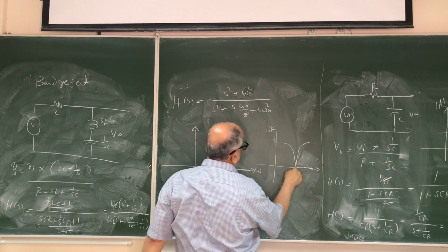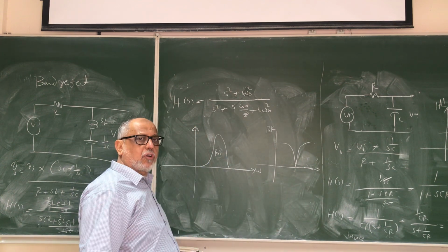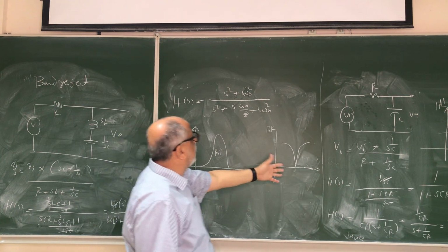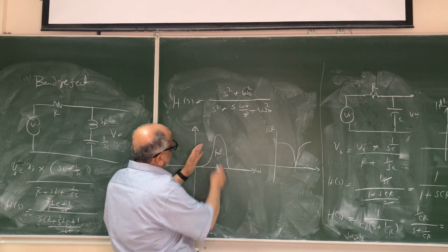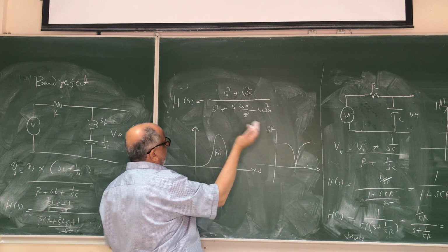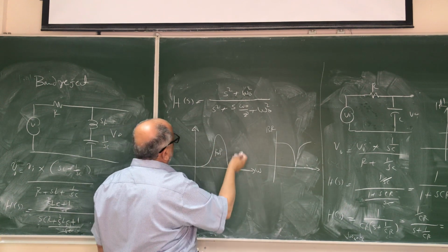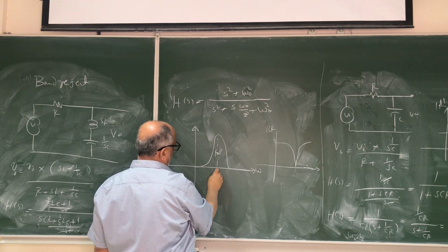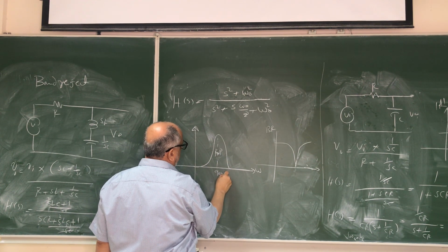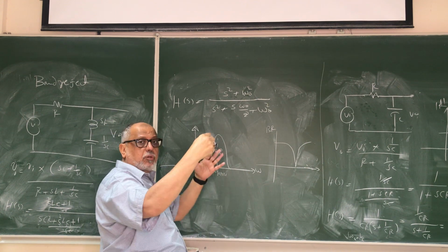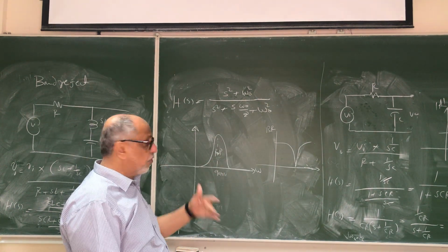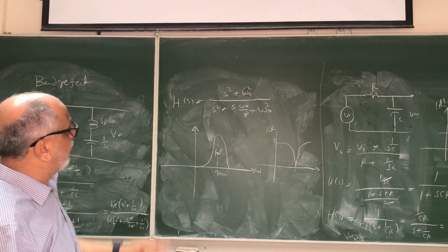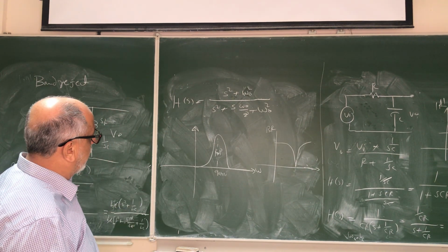So you are eliminating or rejecting a certain noise. Like the 60 Hz I want to eliminate, then you can use the band reject. If I want to pass a band of frequencies like the FM 106.1 or 90 megahertz, then I can tune my filter or design my filter so that this is 90 megahertz, and I can make it sharp so that I cannot hear any other frequencies coming from other stations. So this is basically the 4 common types of filters we have to know about.